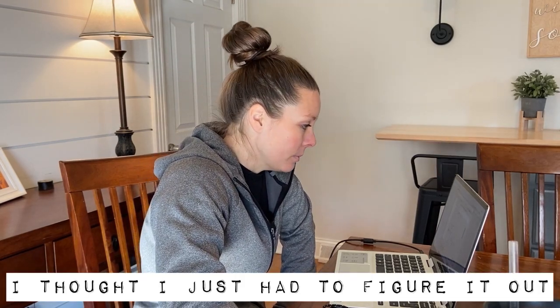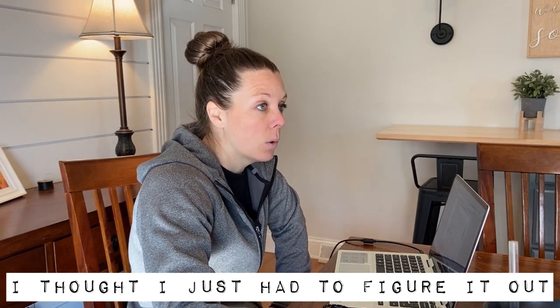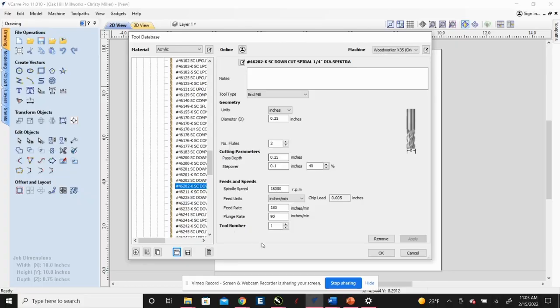When everyone's talking to you about speeds and feeds and tool paths, this is huge. The manufacturers of these bits have essentially tested them to see what is a safe speed and a safe feed and a safe pass depth and a safe step over and all this information for you so that this is a good starting place. It doesn't necessarily mean these are the fastest settings, and you have to do your own due diligence over time, but this is a starting point and you don't have to worry about it. So that's why this is an incredible tool to make good use of.